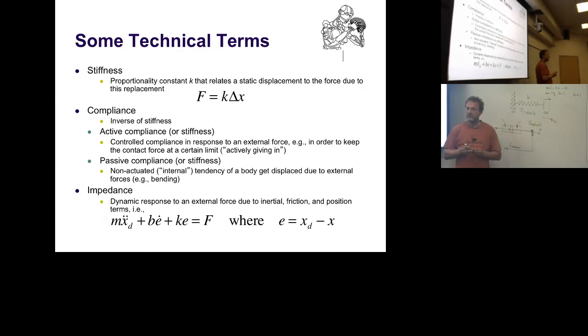And then I simply prescribe: when I move my end effector, which is characterized by some x double dot, I want it to behave as if it were a 1 kilogram system with very little viscous friction and a little bit of springiness. And you can make the robot behave like that.